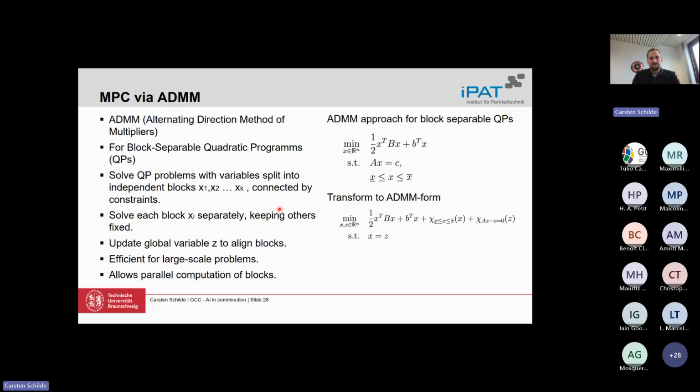So what is this system doing? The system uses the population balance method and brings all dependencies down to several blocks. So for example, the dependency of our final result on the tip speed, the dependency of our final result on the throughput, or the other parameters like the temperature, for example. These are sub-models, and these sub-models will then be solved independently.